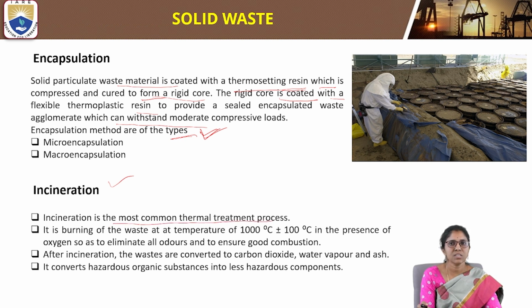The incineration process is a thermal treatment process. It is the burning of waste at a temperature of 1000 degrees centigrade plus or minus 100 degrees centigrade, that means 1000 to 1100 degrees centigrade, in the presence of oxygen, so as to eliminate all odors and to ensure good combustion.